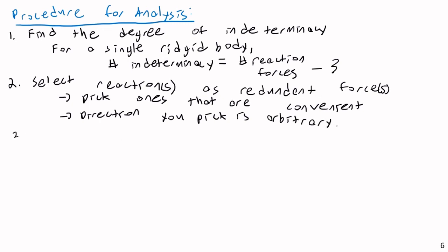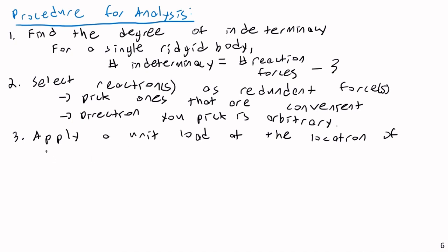So step 3, apply a unit load at the location of the redundant.